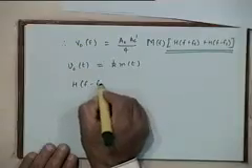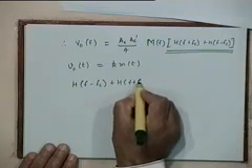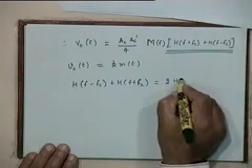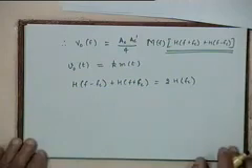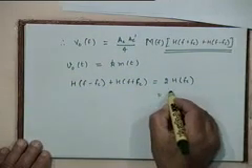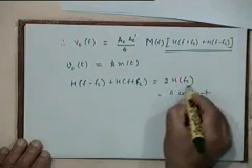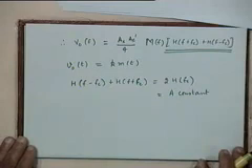That is the condition we are looking for, that H of F minus FC plus H of F plus FC should be a constant. Let's for convenience call it twice H of FC, because it doesn't matter what you call it. It should be basically a constant, and for convenience I'm just saying that let that constant be equal to twice the value at FC, right?